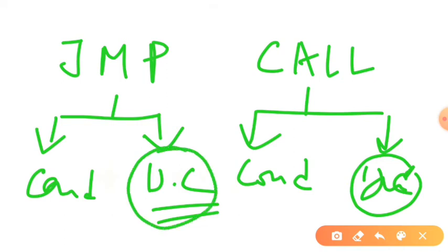Another type is called conditional. This kind of instruction checks the status of different flags. It may be the carry flag, the zero flag, the parity flag, or the sign flag. So depending on these flag conditions, the next instruction may be fetched from the next memory location C003, or it may be fetched from the address specified in the instruction itself, C050.